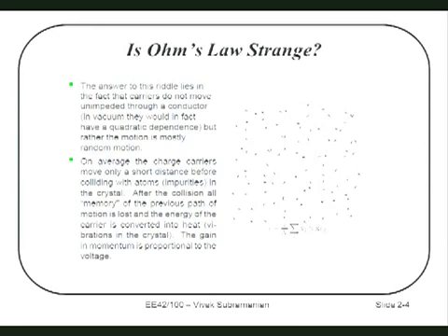It turns out if you average the ensemble of all of these electrons with all their different velocities, and you do an ensemble calculation over the entire number of millions or billions of electrons in your system, you will end up finding that because of the averaging effect, the square behavior goes away and you end up with linear behavior. Okay? If you had a single electron and the electron was not perturbed, the velocity would indeed show a quadratic form, and therefore the current would show a quadratic form.